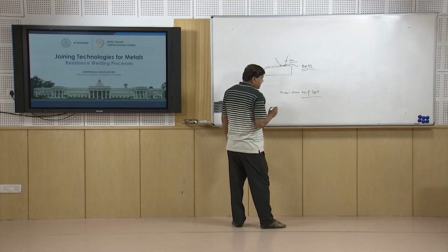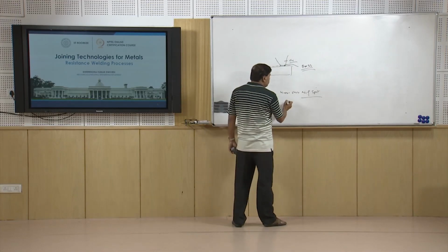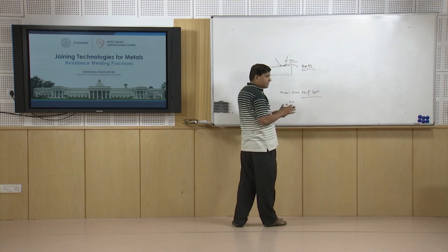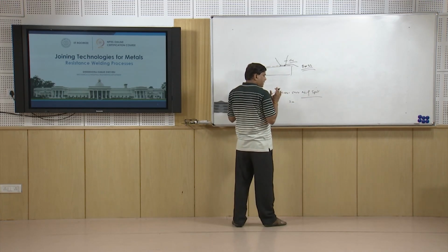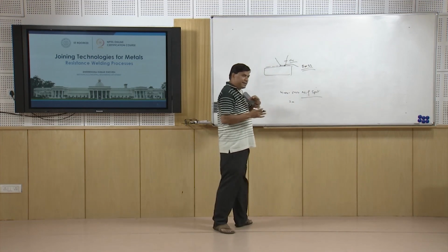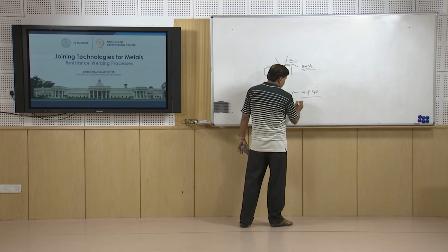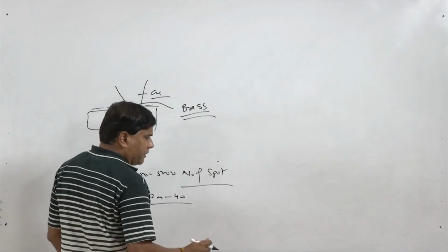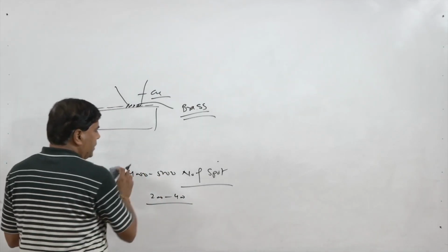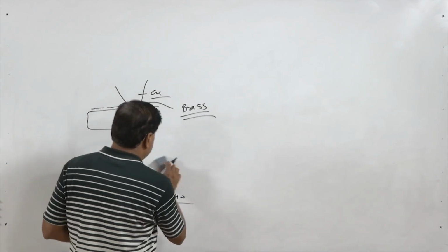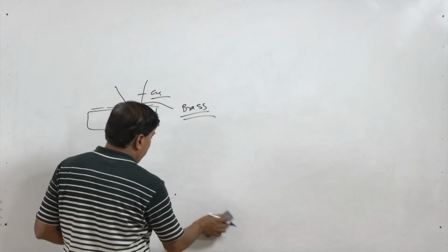When the zinc coated steels are spot welded, you may find that after like 200 spots, the diameter gets modified and enlarged to such an extent that it needs replacement or refurbishing, so that the same size of nugget diameter can be achieved.